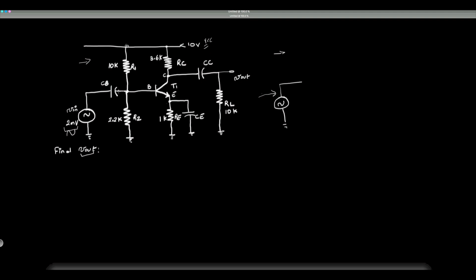And so if this is the base, for example, this whole line, all of this is the base after the capacitor. We will try to see what this component looks like, what this component looks like, etc., as we move from left to right. So first of all, we're encountering this capacitor, right? I could draw a capacitor right here, but given a certain frequency f, we will assume that this capacitor's impedance will be almost zero. All right, this here is a coupling capacitor.